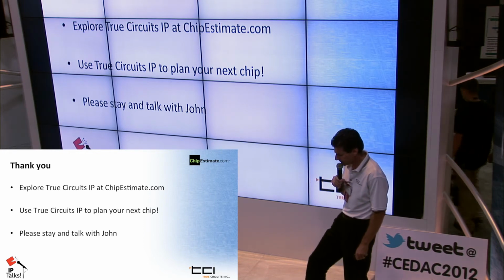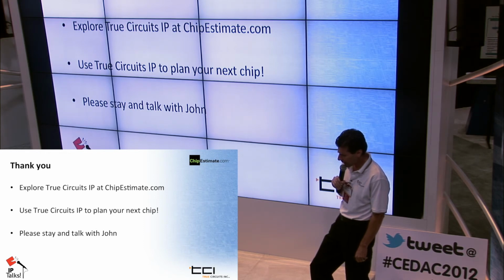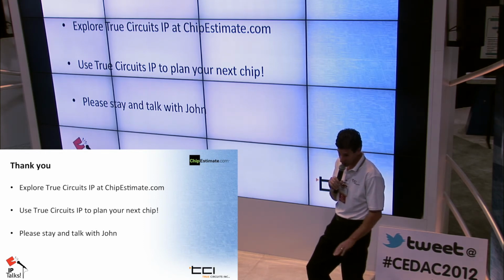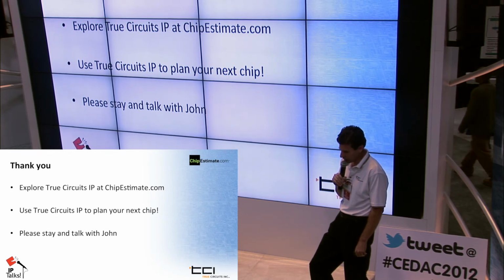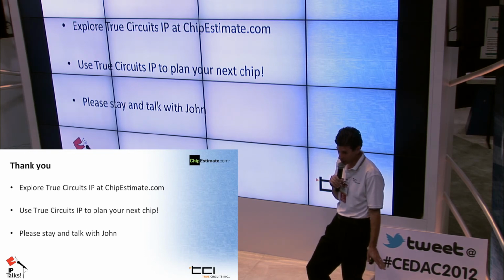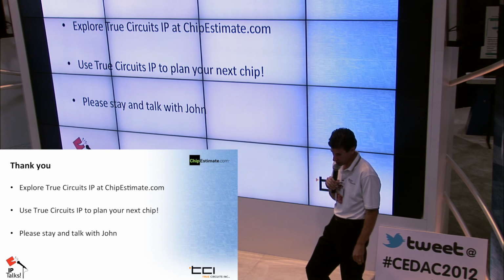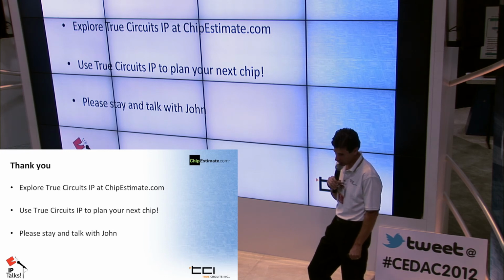Yeah, so the designs have some amount of digital logic, and then a lot of analog circuitry. Most of the analog circuitry is characterized directly in SPICE. Though for some of the more complex designs, we do functional verification through mixed mode simulations. They're not so complicated that we need to do things like static timing analysis. Instead, we can just cover everything with a large set of vectors and make sure that we haven't missed anything.